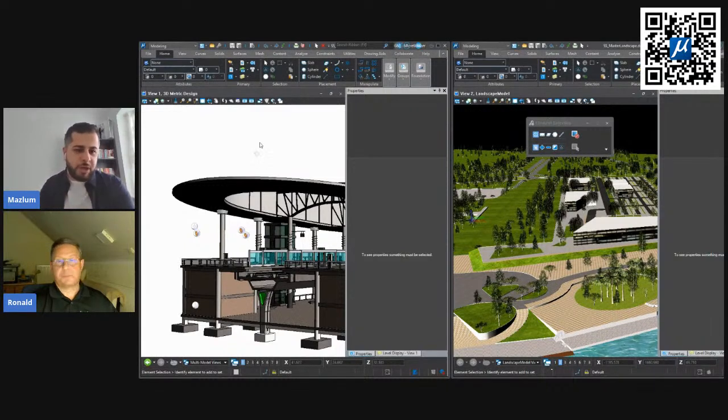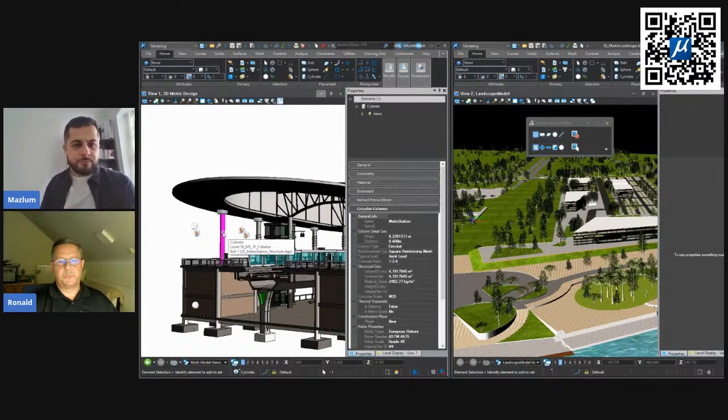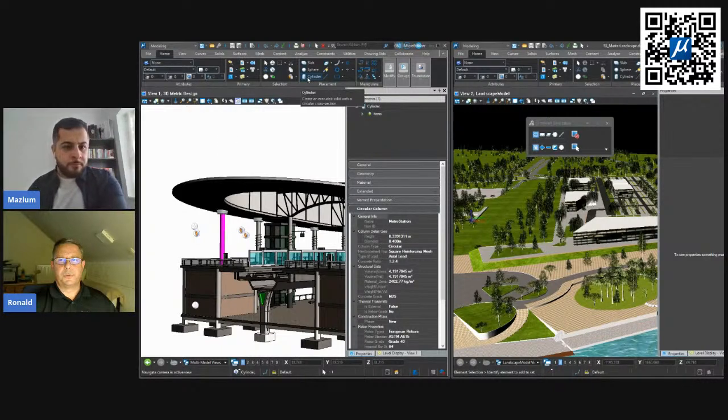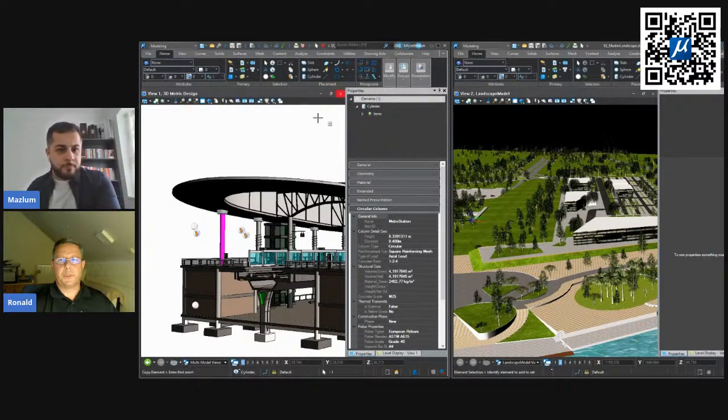So essentially it kind of works as tabs, but you do need to open two different windows. It doesn't have to be in the same program instance. I can select the element here. Okay, this element is not in my drawing. It's an XREF attachment, so I have to do a local copy first. Let me do this very quickly. Now it is part of my DGN file, and I don't have write access to the XREF attachments.